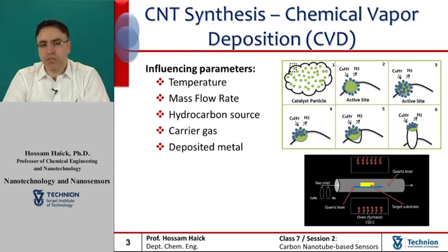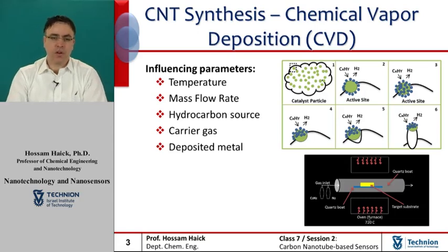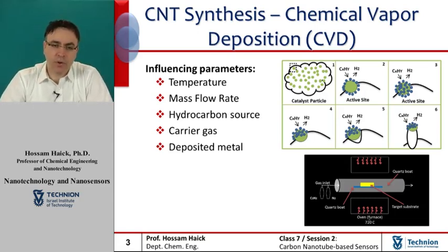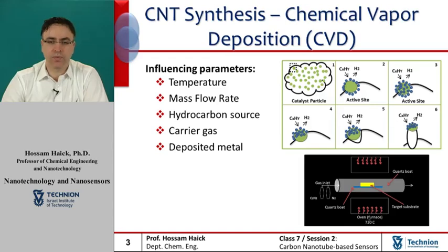Numerous parameters influence the carbon nanotube growth. One example parameter is the metal catalyst. The function of the catalyst in the CVD process is the decomposition of the carbon source throughout the plasma irradiation or heat, namely thermal CVD, and its nucleation to form carbon nanotubes.